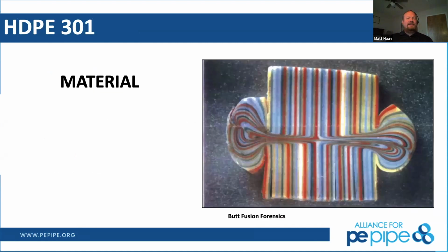The key is that the performance properties of the material remain the same. In a thermoset environment, you may be able to heat fuse or create in a process, but the pipe itself has to be cured. If you were to melt it again, you would have to re-cure it to obtain the same material properties. That's what sets them apart.